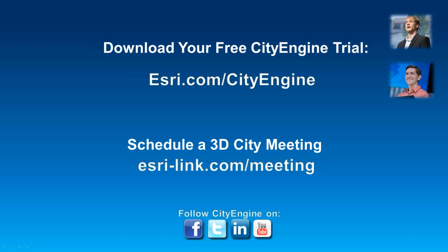So another question was concerning ArcGIS 11, and is it compatible with CityEngine, and what are some of the overlaps? 11 has the procedural core that's inside of CityEngine also installed within it, so we've fully integrated some of the procedural capabilities there, and you can write rule packages or RPK files that can then run inside of ArcGIS 11, so you don't have to do all the work from CityEngine. And whenever you update a building attribute or a street attribute, the geometries adapt to those changes. All you have to do is run a GP tool, a geoprocessing tool, on the 3D models there.